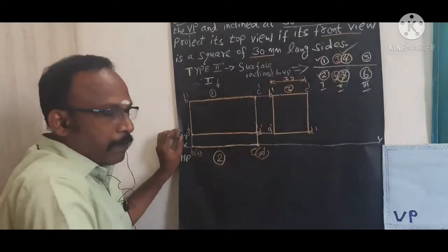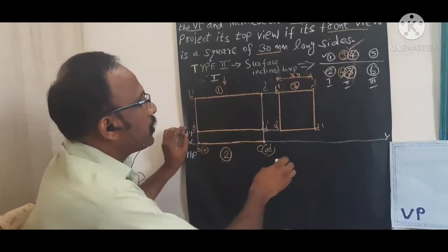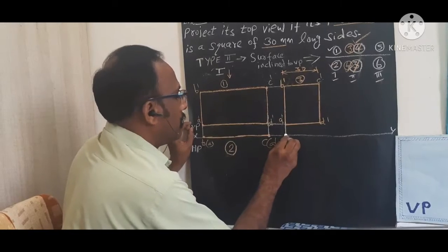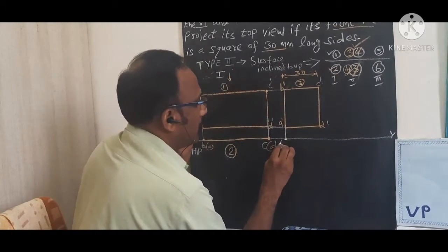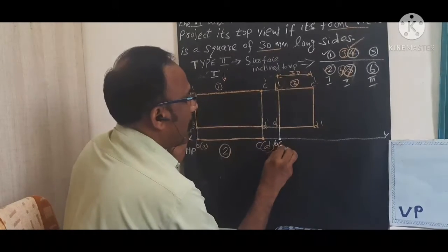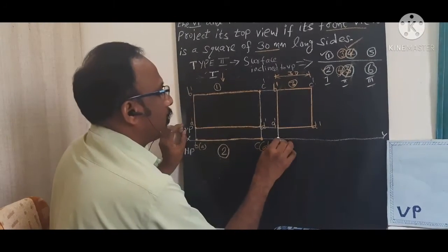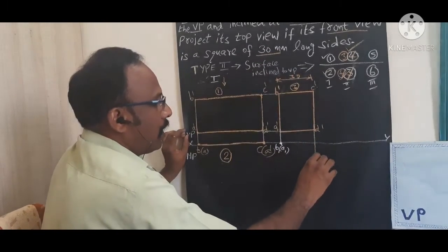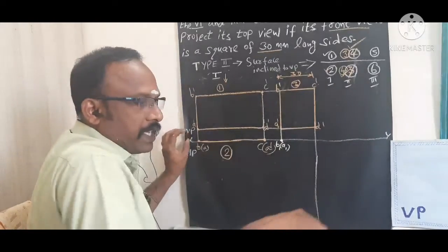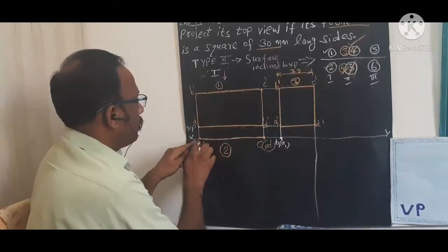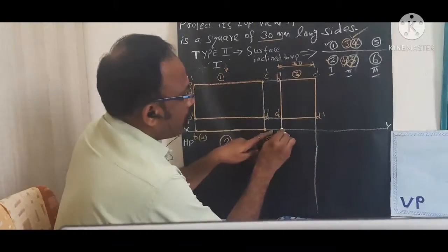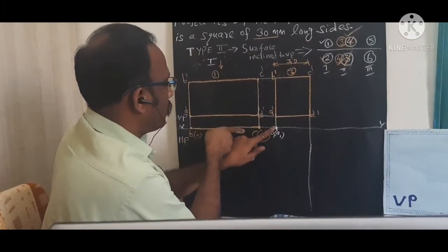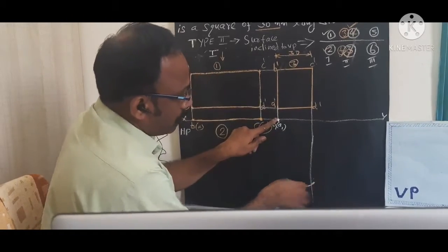Now I am going to step number 4, for which I need to draw one projection line from here. That point is to be marked here as B1 and A1. I mark this particular point, and through this point I am going to draw one vertical line up to some distance. Now take the compass for this distance BC. Now take this point. By the compass you need to cut the distance we measured, BC. By the compass you need to draw this arc.